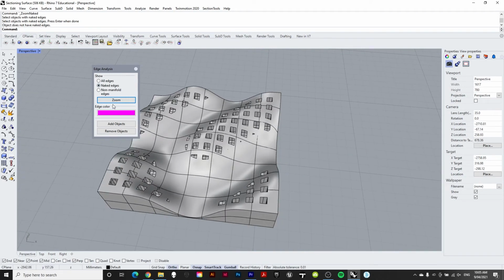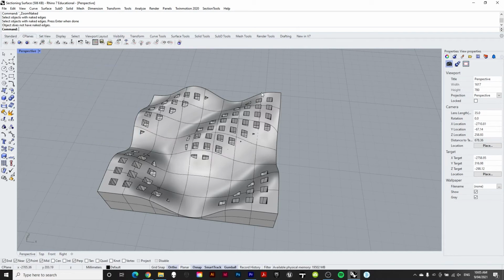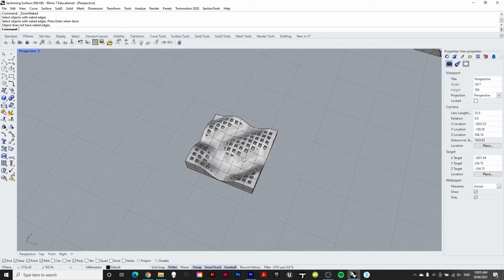This would come out pink for you, and then what you would need to do is make sure that you join them together. You can always do a match surface or a blend surface just to try and make sure everything is closed up, ready to go. And you join all those together and close all of your loops.